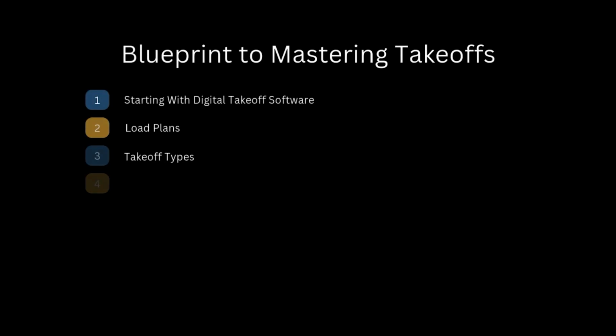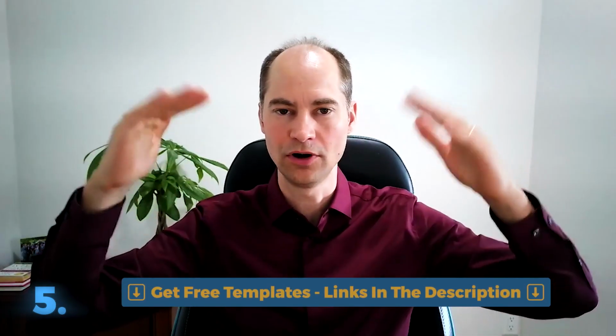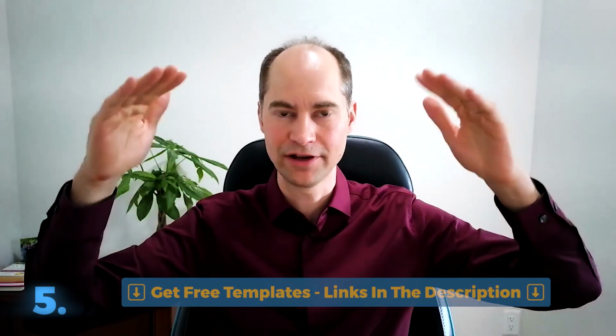All right, moving on to point number 5, the one everyone wants to know, how they can go quicker with doing takeoffs. So the first thing is make sure that you're following a template. So have a template for your estimate with all the different line items and have it in chronological order. That's the way I like to organize it. And then just follow your template and do takeoffs as you get to the different items in your template.